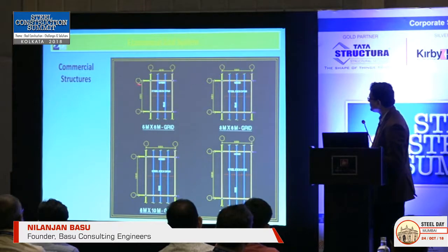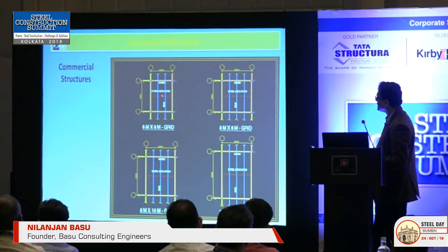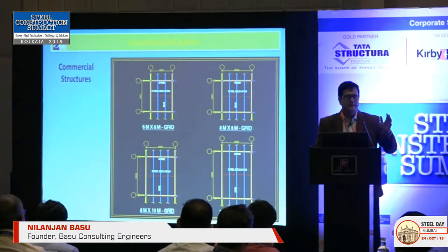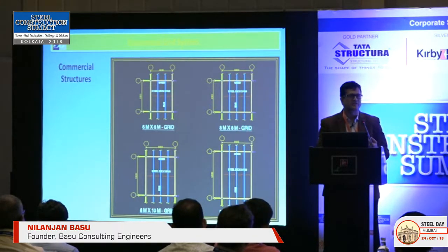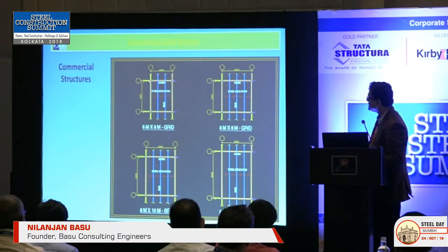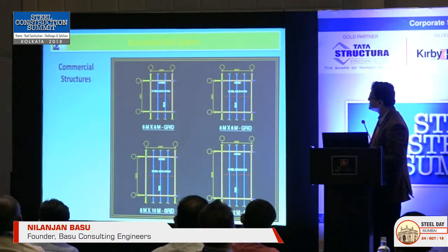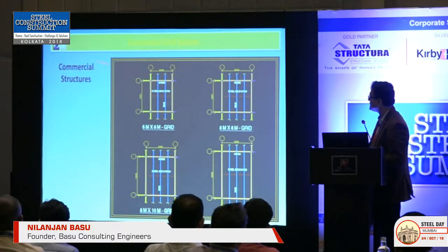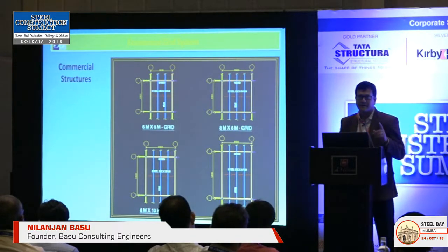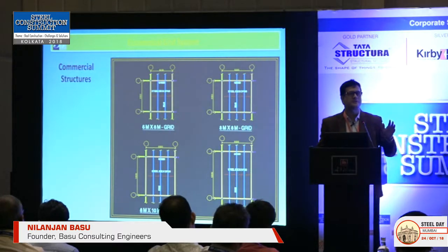And if you see again, the beam system generally frames into the shorter beam. It doesn't frame into the longer beam. Why? Because we don't want to compromise with the depth of the beam which is transferring the load. So these transfer beams then transfer to the main girders. We use the transfer to the shorter girder, which then connects to the column flange. So this beam, actually, it's a longer span, but it doesn't take so much load, so that we restrict on the depth of the beam.